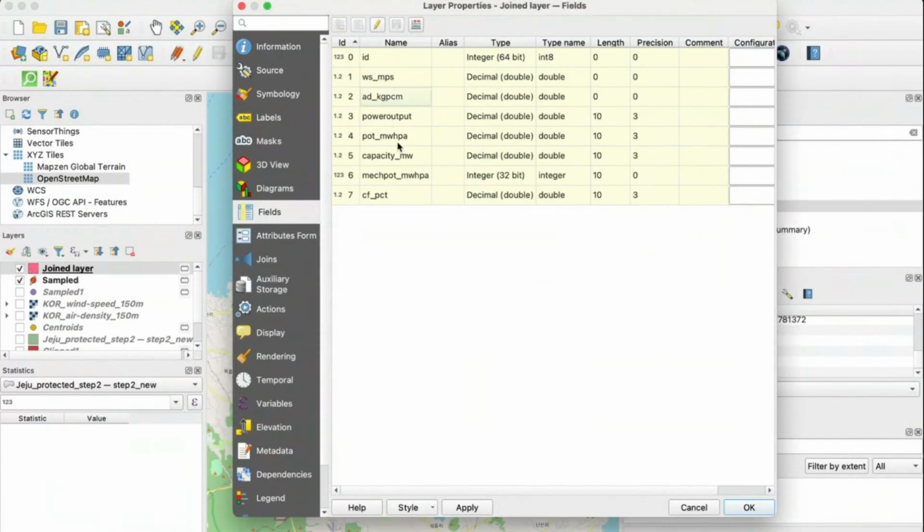It's fine if it looks different in your QGIS, it's totally fine. But I tend to remove unnecessary data whenever I see it. Otherwise, in the end, you are going to have a huge file with a bunch of trash data. So then go to field calculator.